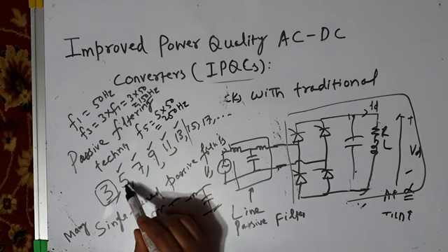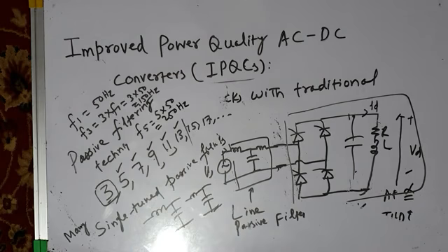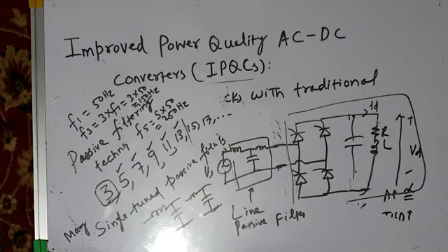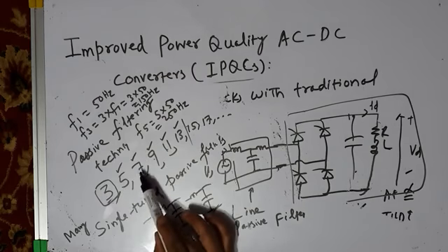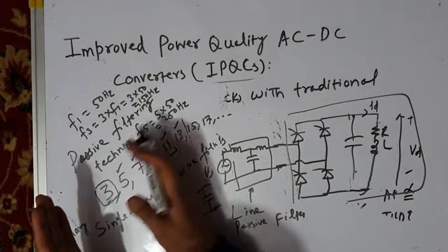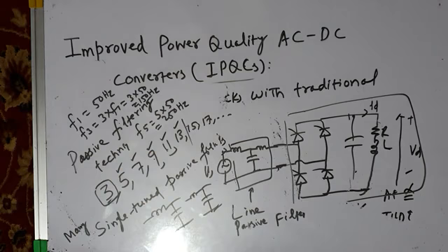the single tuned filter, which is tuned to fifth harmonic component, will be smaller than that of the third, but it will be still higher. Similarly, the size of 7th harmonic single tuned filter will be smaller than these two filters, but it will be still higher. The size of these single tuned filters will be very large.